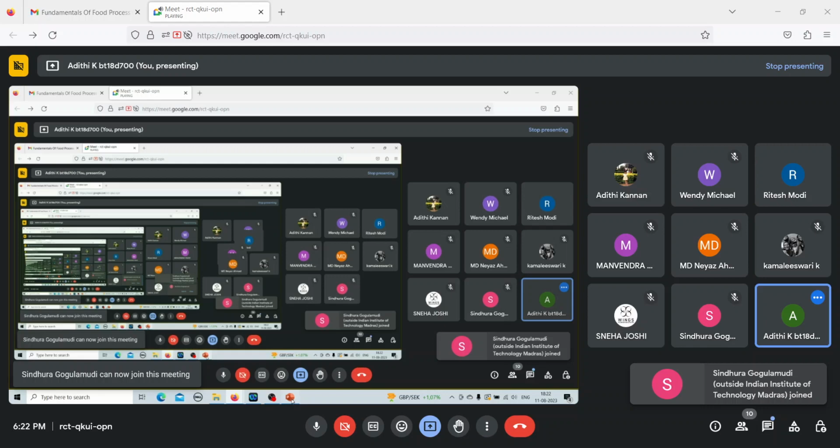It is very similar to the previous question that we tried, where we were looking at the change in concentration. There we used half-life of a reaction. Here C equal to C naught by 2. Here we are looking at the decimal reduction time, which is C equal to C naught by 10. So those are two different concepts, but the overall approach is the same. First we find out what is the reaction rate constant. From there we substitute and find out what is C by C naught.